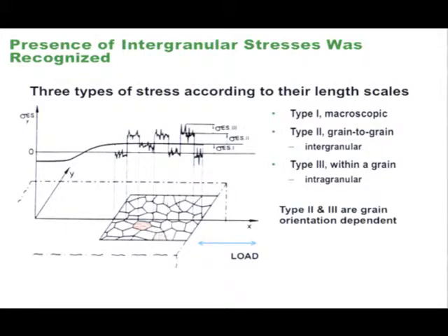And because the grains have different elastic properties and so on and so forth, this incompatibility creates a partitioning of stress. So in addition to this average stress, you have some fluctuations of strain or stress that vary from grain to grain. So the strain in a grain with, let's say, 200 parallel to this direction would be different from 200 oriented in a different way.